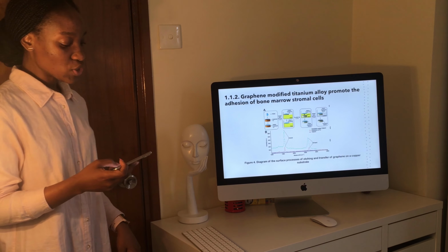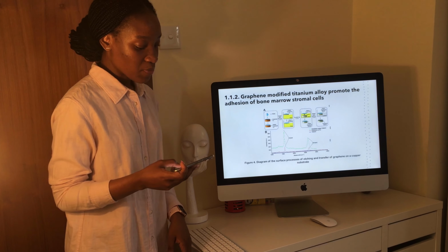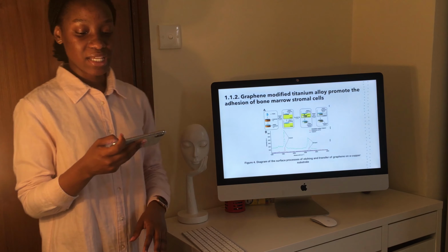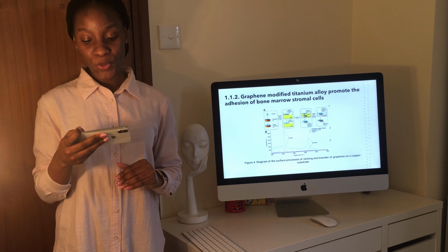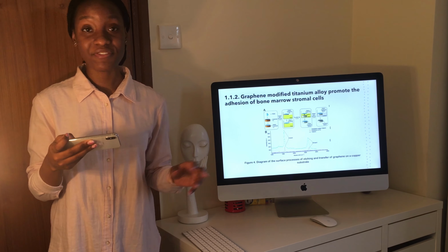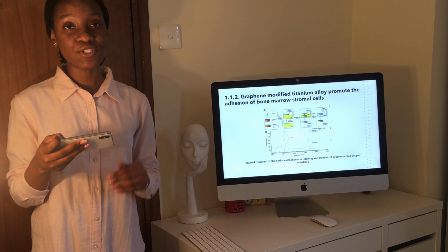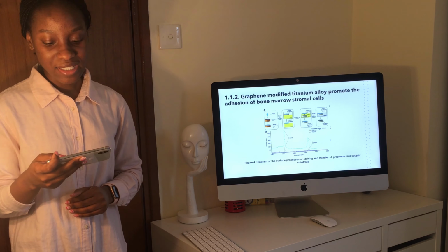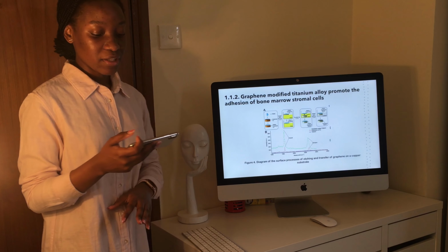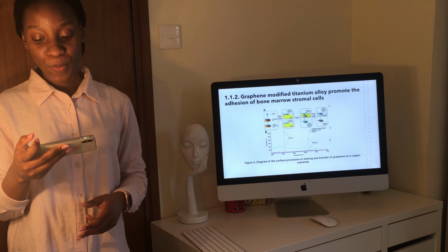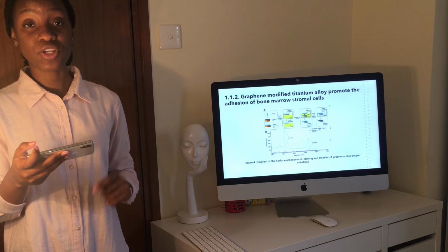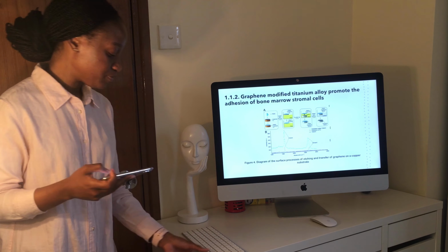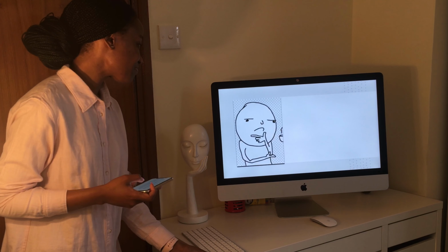Now, onto the graphene modified treatment. This schematic is a brief representation of how the analysis was conducted by applying a surface treatment coating of graphene technique on a grade 5 titanium alloy to assess the aptitude of the material in a biologic system. This study in particular followed a quantitative causal comparative research design by collecting the data of graphene coatings that were prepared using a CVD technique, chemical vapor deposition.